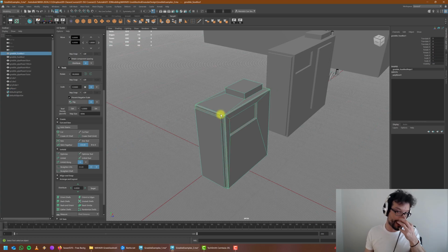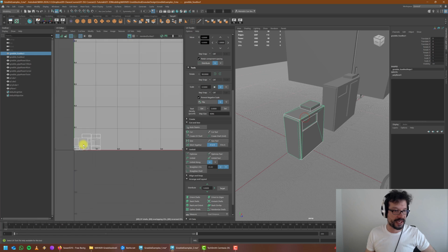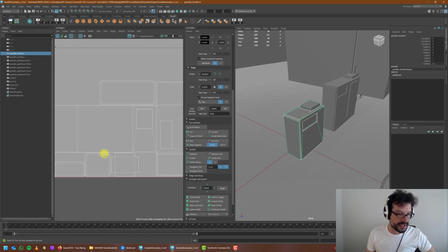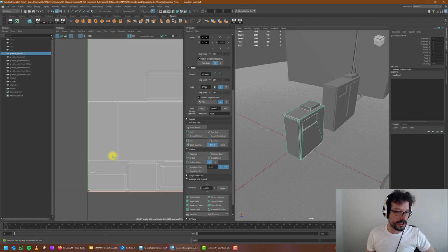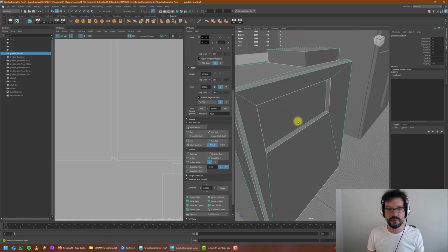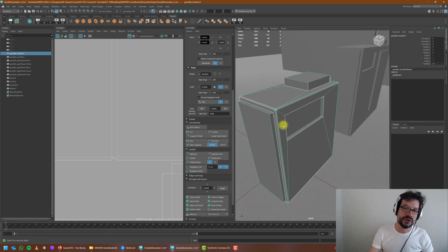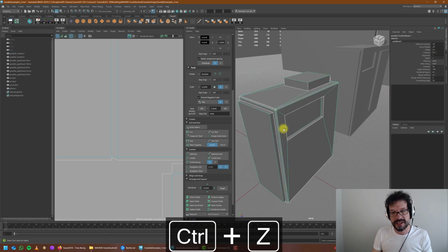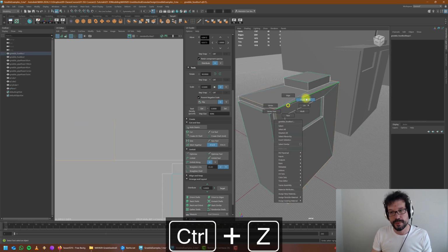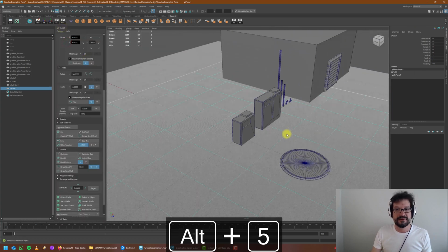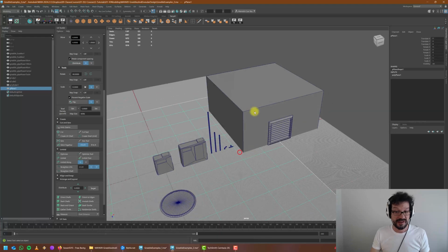There's absolutely no reason why you should be beveling these corners or beveling these edges. Not to mention that it will complicate the UV process as well. Now you will have to go in and fix all of these edge alignments so that the bevel itself works. You will be creating additional faces that you need to play around with in the UV unwrapping procedure. Okay, so it's entirely up to you, but know that many different approaches exist.